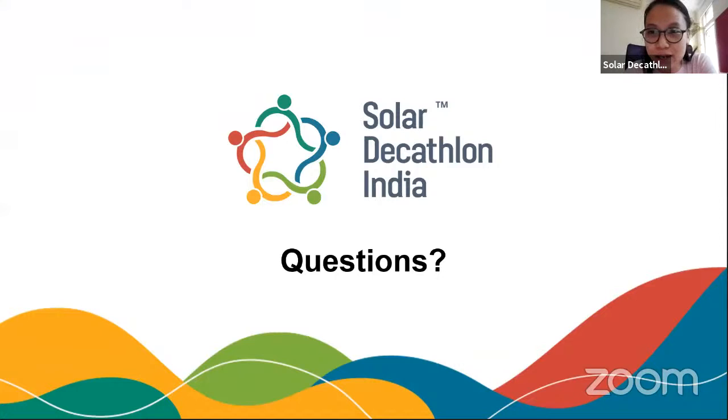Okay. So Mansi, your first question is, in your presentation, what is resultant temperature? Is it the same as operative temperature? Correct. So resultant temperature, I would say, is an operative temperature, which is an average of air temperature and the radiative temperature. I can confirm that in DesignBuilder, you will get operative temperature, which is exactly what Mansi said, which is the average between the air temperature and the radiant temperature.